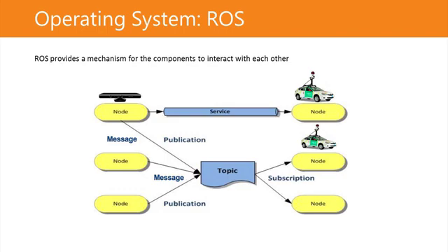So what is ROS? ROS is actually a middleware software component that combines different pieces of software together. The main task it provides is communication. For example, if you are a node in ROS, you can publish your results through a topic, and then different nodes will subscribe to the topic. In this example, the publishing node can be a camera, such that each time it has an image, it pushes to the topic. The subscribing node can be a perception pipeline that uses the camera information, and it can also be the localization pipeline that uses that image information for positional updates. So both the deep learning pipeline and the localization pipeline use the camera information. You can do this through a topic, and you can also do dedicated service, point-to-point communication as well. That's the beauty of ROS: it provides many different communication mechanisms.